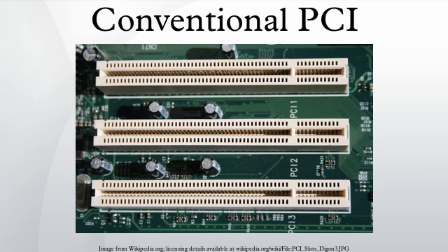For reads, it is always legal to ignore the byte enable signals and simply return all 32 bits. Prefetchable memory resources are required to always return 32 valid bits. The byte enables are mainly useful for I/O space accesses where reads have side effects. A data phase with all 4 CBE lines deasserted is explicitly permitted by the PCI standard, and must have no effect on the target other than to advance the address in the burst access in progress.